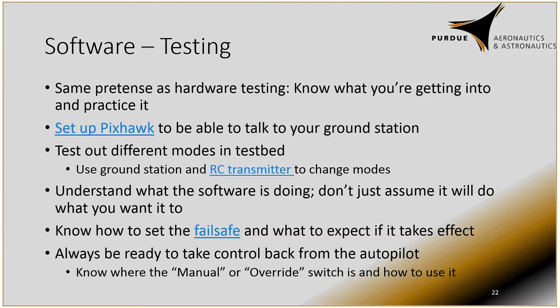I absolutely know what the fail-safes are and what to expect. When they will trigger, why they will trigger, what to do if they do trigger, all along those lines. And always be ready to take control back from the autopilot unless you've flown your mission tens of times and you know absolutely what it's going to do without any question.